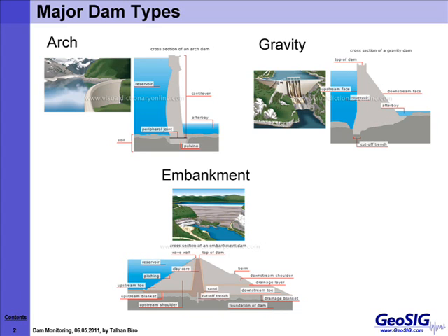An arch dam is made out of reinforced concrete structure, which is in front of the water, holding the reservoir back, and it is bent like an arch. That's why it's called an arch dam. They are basically holding the water back by the structure's properties, this arch structure, and they don't really need a huge space to be made.